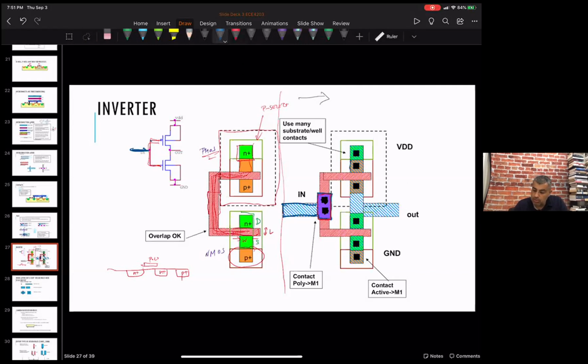Okay. And then we've also gotten some metal 1 here for this guy. Metal 1 here for this guy. And this metal 1 here for the output. And for each one, you've dropped a contact, contact, contact, contact. So those are the contacts. Okay, everybody sort of see that?